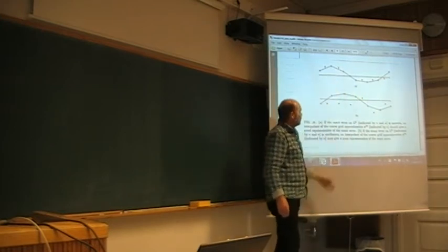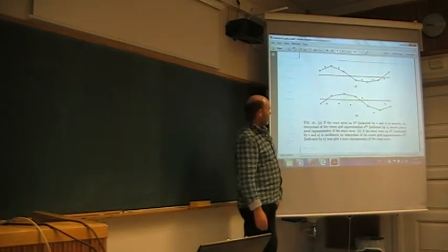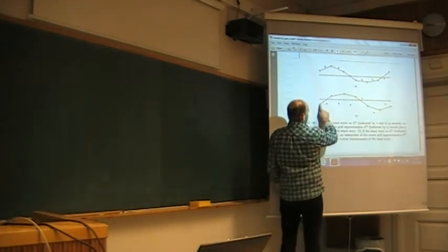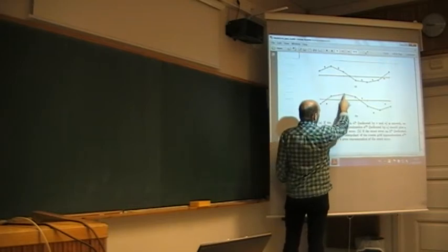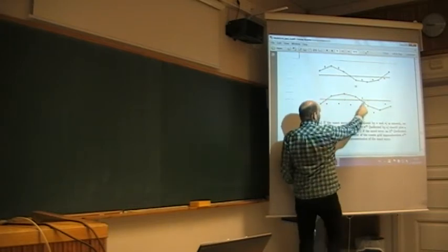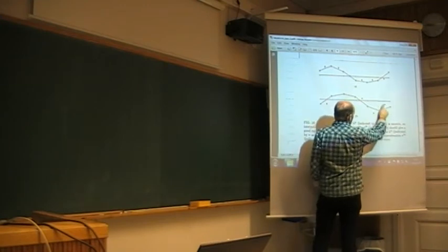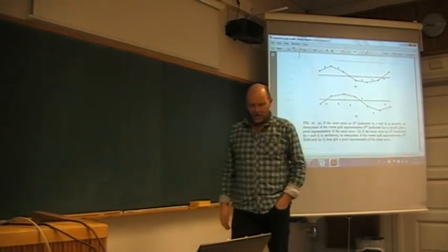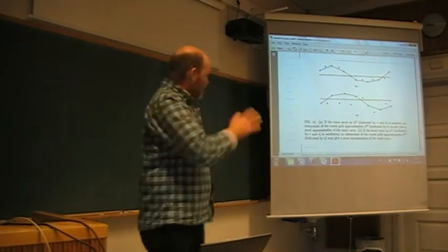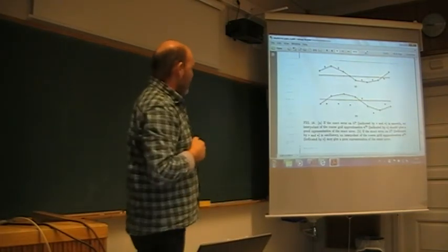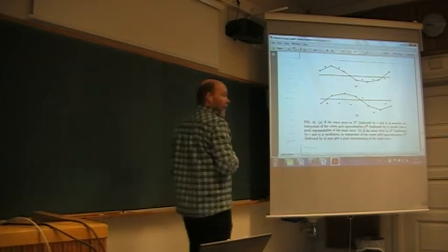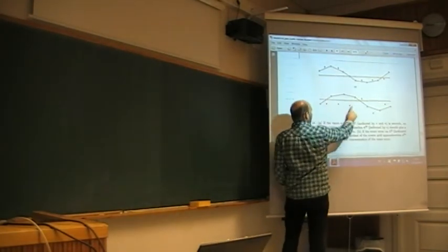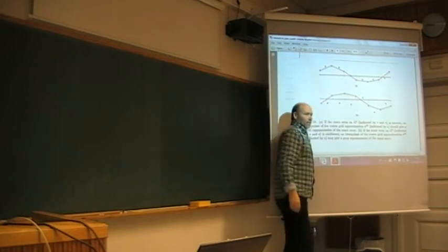But here, if you have on the fine mesh a rather strange signal going a little up and down, something like this, down there, there, there, and then pick every other point, all of a sudden you get a signal that appears smooth, and it is definitely a very, very bad representation of the original signal that you had. That was very high frequency.